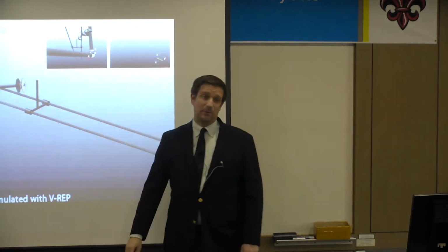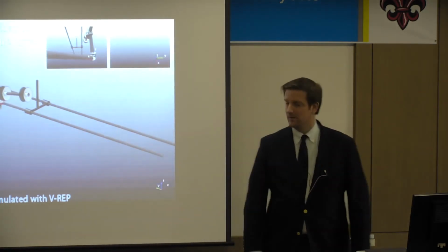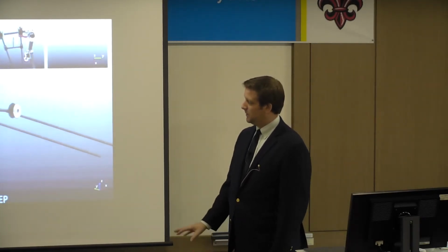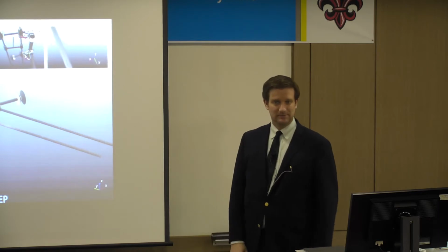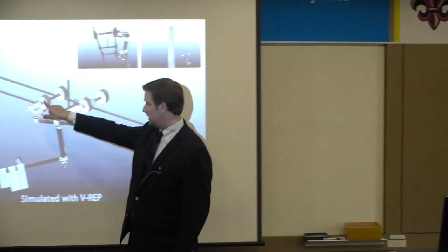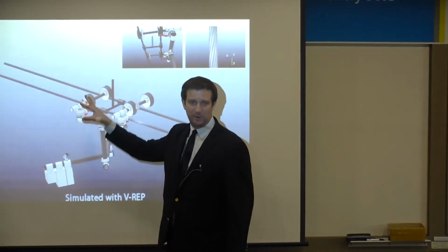So we take this system and apply input shaping to that driving. We take that same system, and this is a full simulation, and we stop: no vibration. So we basically just applied input shaping to the driving of these pulleys, knowing what the rocking frequency was.